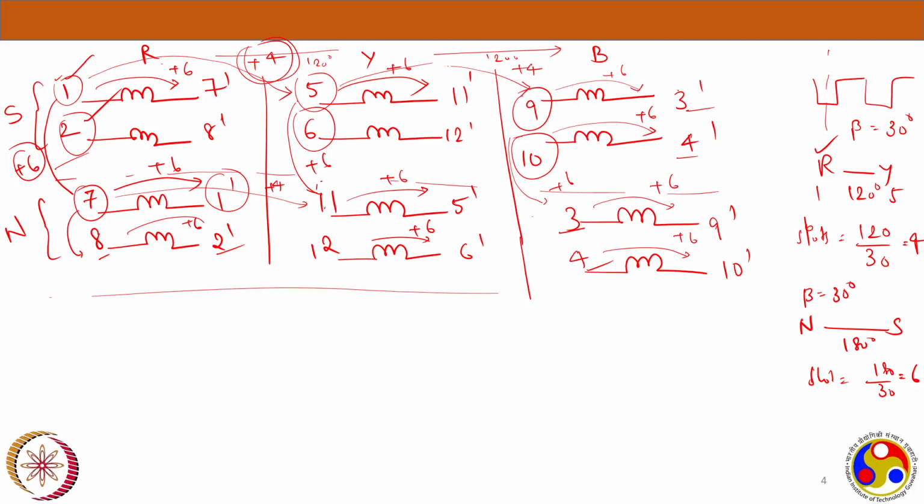So that's it. This is how you place a three-phase winding. But now the important thing is how you will join them. Placing the winding is not our main aim. After placing them, you need to take the terminals outside, R terminal, Y terminal, B terminal, so they should be available for giving the supply or load, right? That's how you have to give the supply and you should get the maximum voltage as an output.